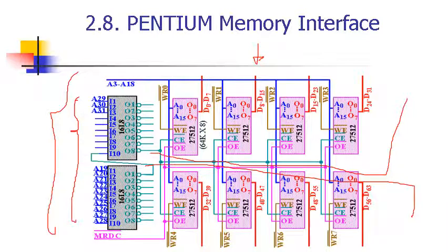For example, here, as we said previously, we have 8 banks, so we dedicate the 3 bus bits A0, A1, and A2 to select one of these 8 banks, while the memory, we connect A0 of your memory chip, of your memory bank, to A3 of your address bus, A1 to A4, A2 to A5, up to A15 to A18.